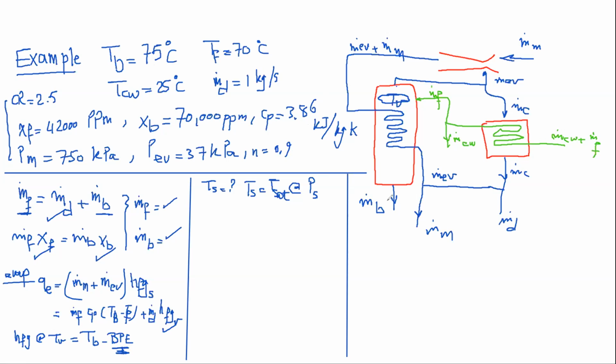If you consider, for example, something like a TS diagram, that I need HFG at a certain temperature. If you go to the thermodynamic table, you'll find that you are given the value HF, HG, and the value of HFG will be given. Some thermodynamic books will not give it, so it will be the difference between HG and HF. Right, yes. So you don't need more than that.